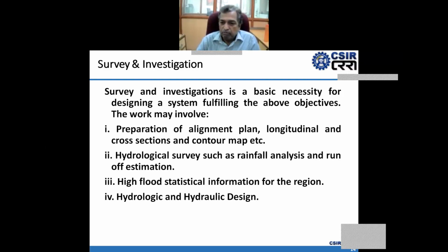Before designing the drainage system, we have to do survey and investigation. For that, we have to prepare the alignment plan, longitudinal and cross sections, and contour map of the area.